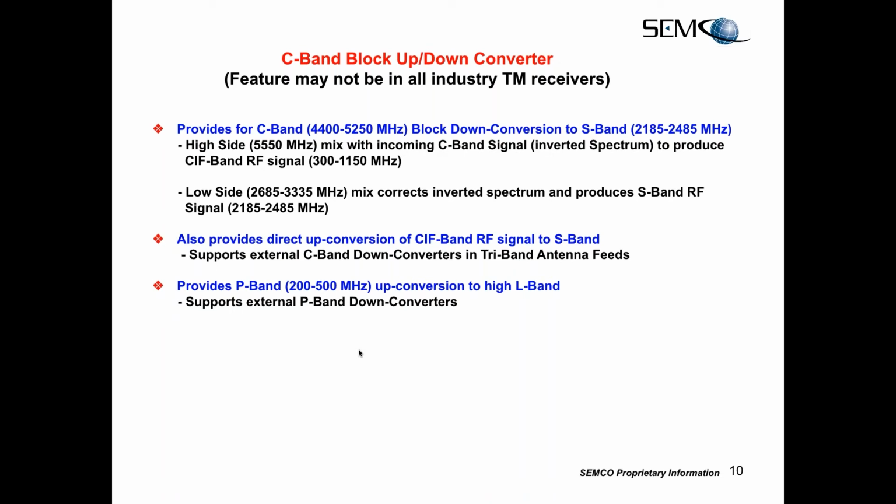So you don't want to have to introduce another C-band RF tuner where you have to go with the LO down conversion process and the filtering process, and again try to run all that at C-band and develop another RF tuner. Plus, it's a very costly approach to do that. So the best approach is typically to just use a block up down converter. A block up down converter is a very straightforward, simple design.